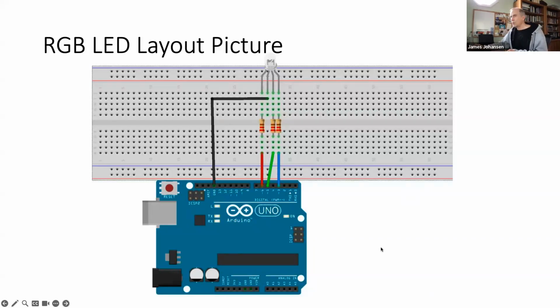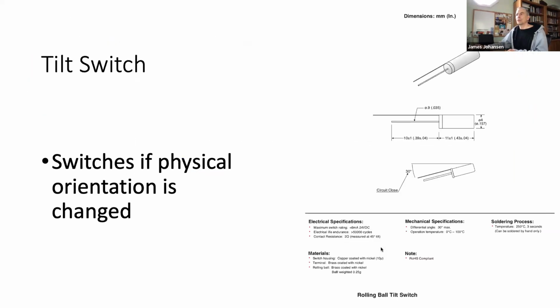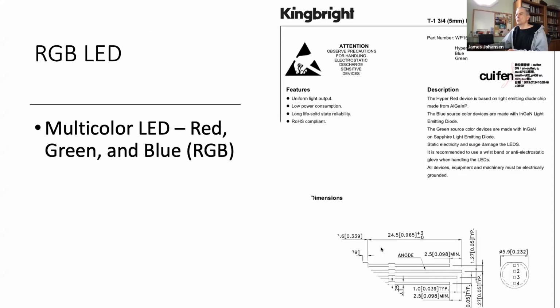And let me go back a few charts because I think I shared it in here. Because you got to figure out which pin is which. And so this is this RGB LED. And if you look carefully, if you were to pull this out of your kit, and I think everybody has this in your kit, you have one lead that's really long, and then they go down from there in terms of size. And what this does, it helps give you the convention of which one is which that you're going to be connecting with which value.